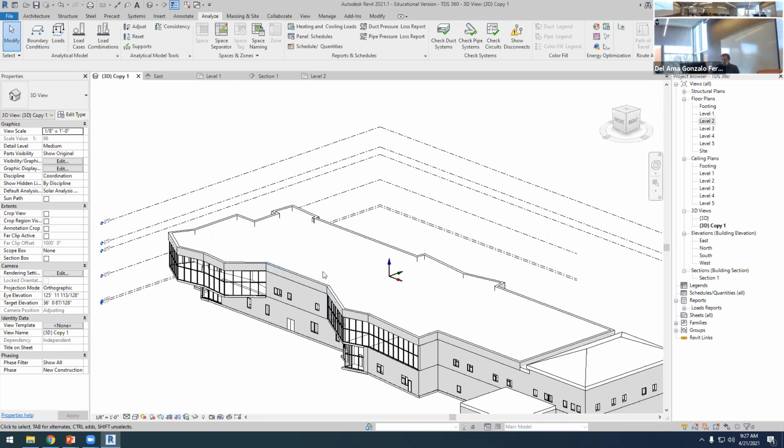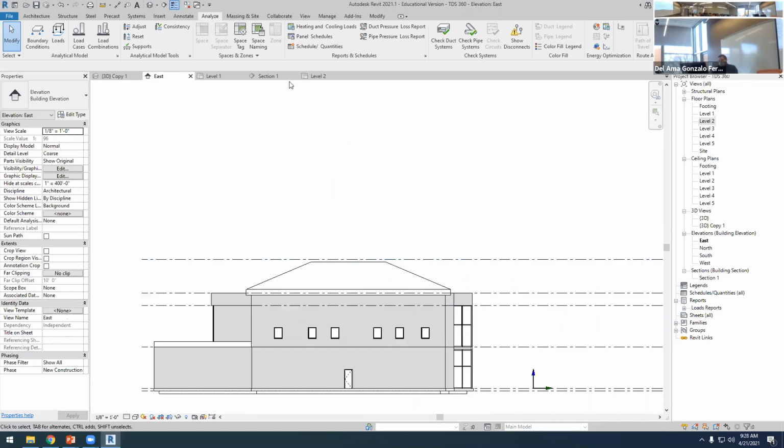We agreed, or we showed, that the optimum angle is around 40 because the latitude of Keene is around 42, 43. So a good angle would be 40. The problem is that if we have an open rack like this with an angle of 40, it will be extremely high, and we can't afford that. So the other option, and I'm sure that they considered these two options, and finally they made a decision on the other one.